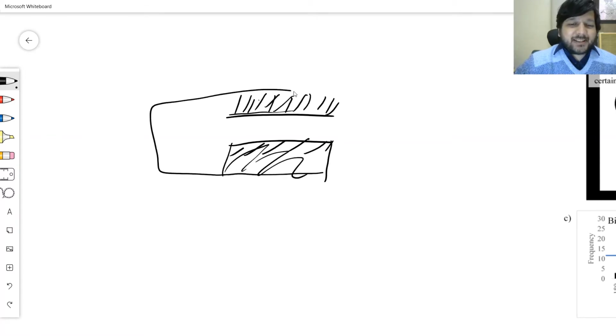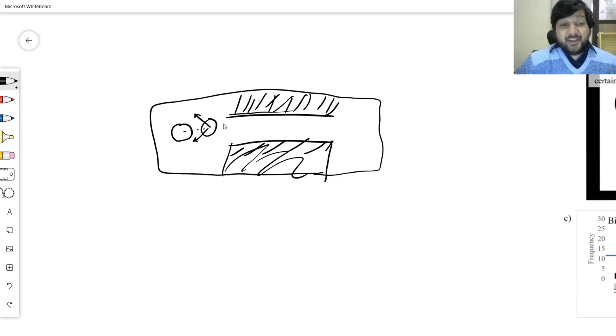But I've got this kind of a map where it's indispensable to enter the corridor, and the robot is pretty big, so it just fits in. As it travels around, it'll get reasonable repulsion from both the corners. It has to come very close to the obstacle corners to enter the corridor, so the repulsion is going to sufficiently cancel out the attraction to goal, and that's a big problem. The robot will not even enter the corridor.